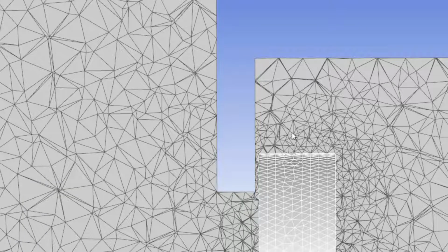Note that when the check valves are in their most closed positions, as shown here, I will maintain a gap of a single layer of fluid cells between the valves and the fluid chamber walls so that I do not have to account for the change in topology that would result from actual contact.